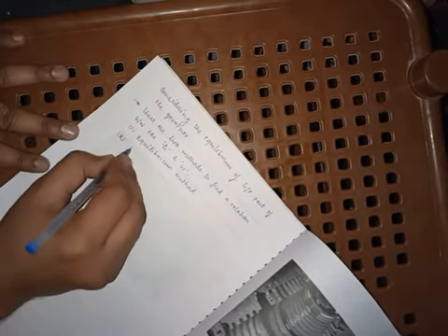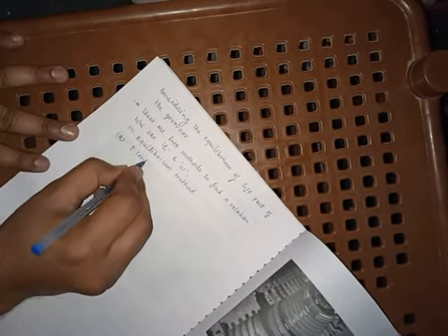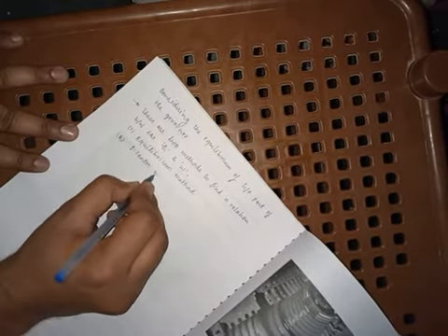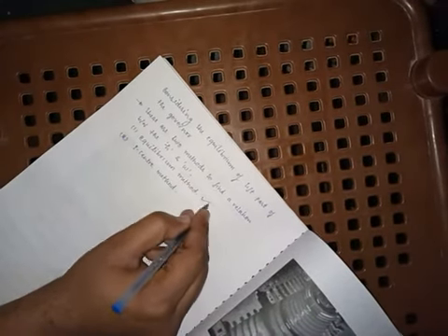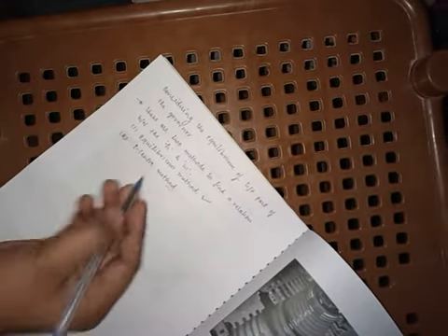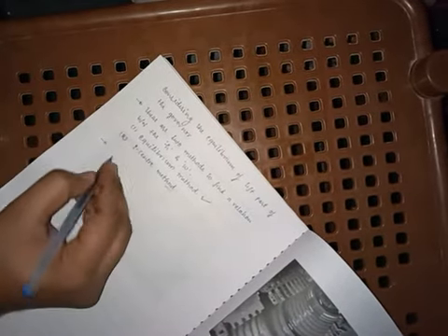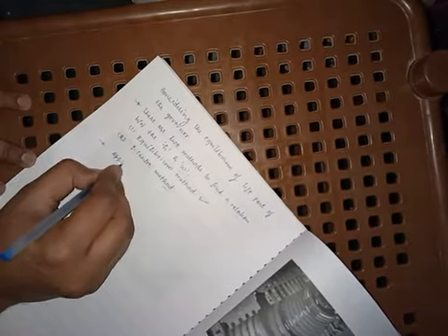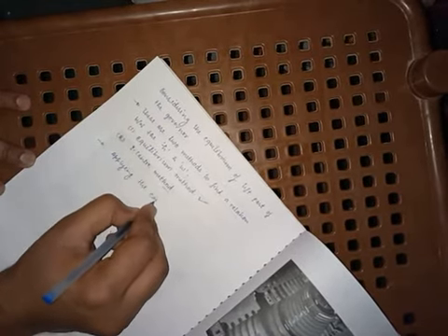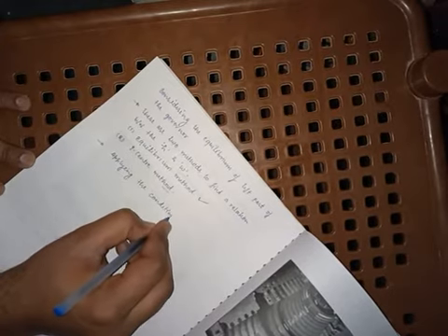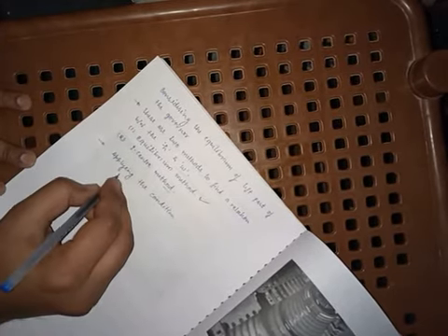We can consider two methods one by one, but in this case we will study this equilibrium method, while the types of governor we will go to this one. So applying the conditions of equilibrium, upward force is equal to downward force, and leftward force is equal to rightward force. So applying the condition, that is T cos theta is equal to mg.